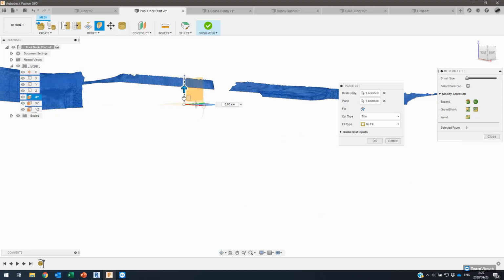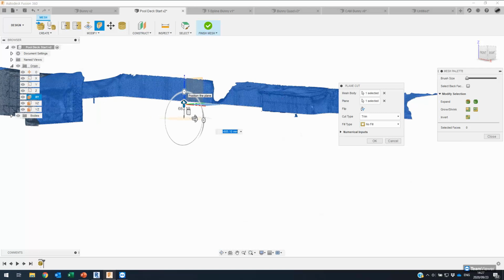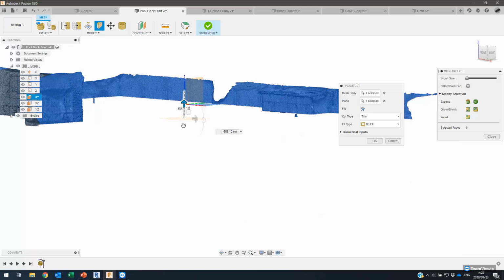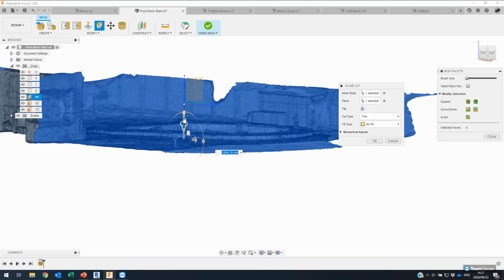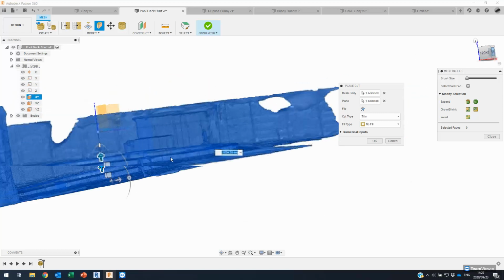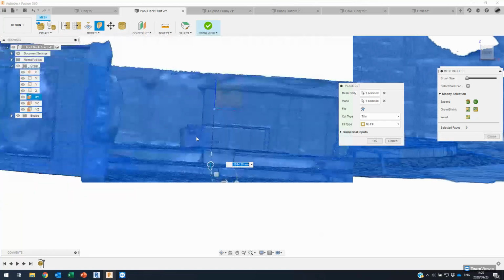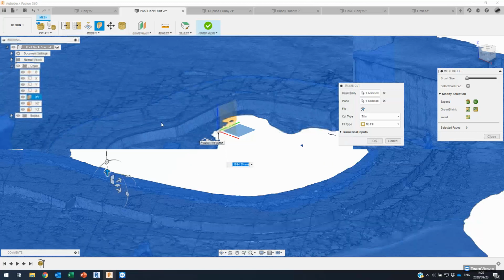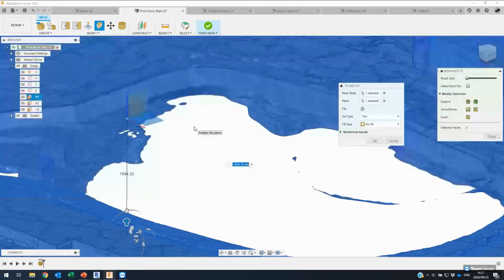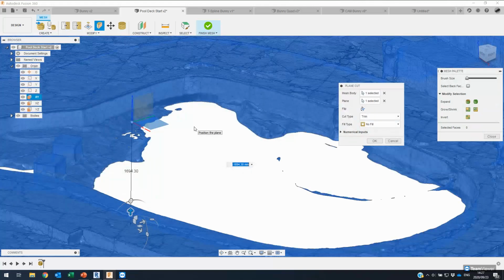and then move that cut plane further down to below the waterline. So this is a rather large mesh, so you can see here now, without reducing the mesh too much, it is a little bit slower to give us the preview. Let me have a look at where we are. Okay, so there we go. We can see that it is removing some of that water below the waterline. So let's see, I'm at 1,609, not 1,700, so I'm going to just round this off.